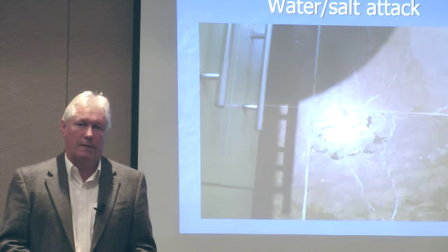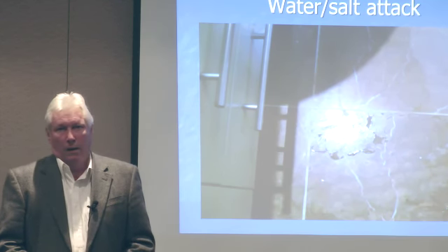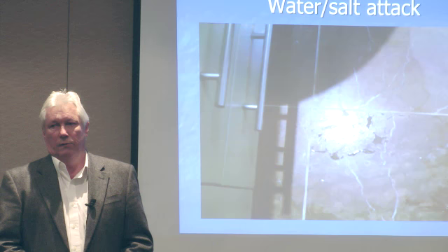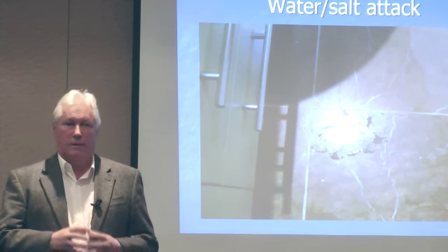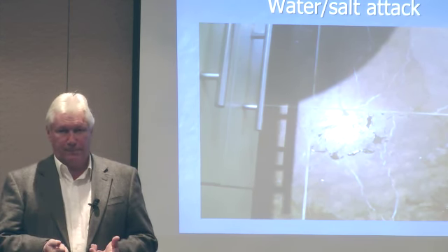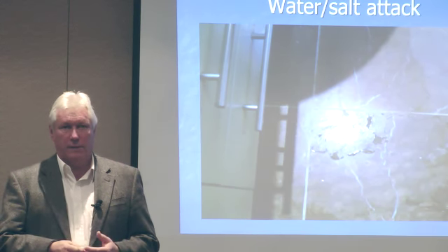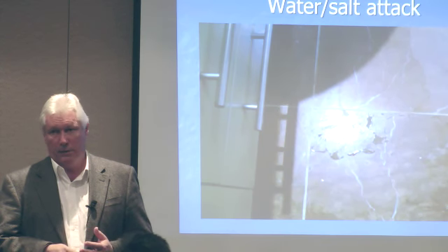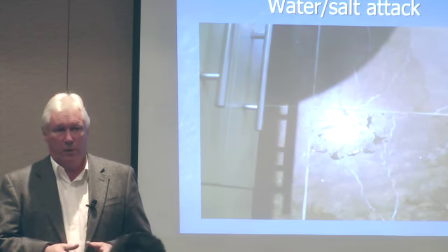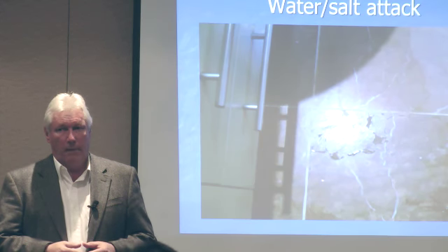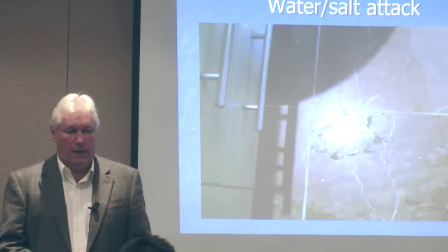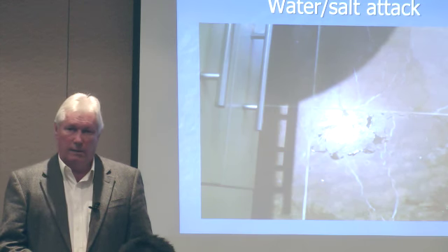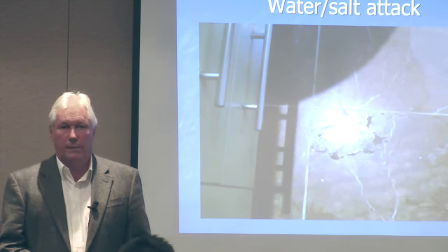In fact, thinking of that particular job, one of the broadest categories of stone that we've got is limestone. So whilst we have granites and they're very hard and they're acid resistant, we have some stones that can be relatively hard but are not acid resistant. Most of the calcareous marbles and limestones will be eaten by even mild exposure to acids. And water will also have different effects on it. So knowing what your stone is going to be important in actually predicting how it's going to perform.